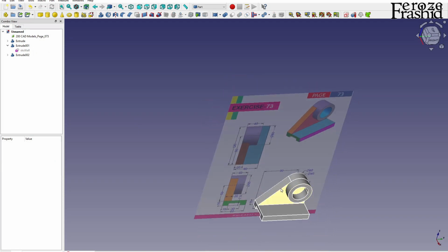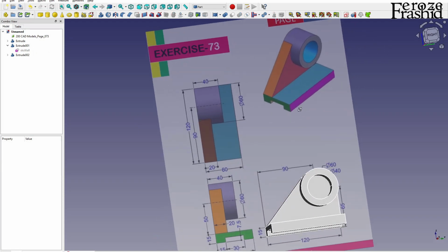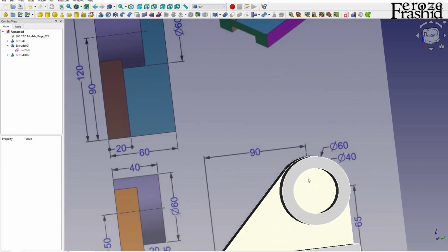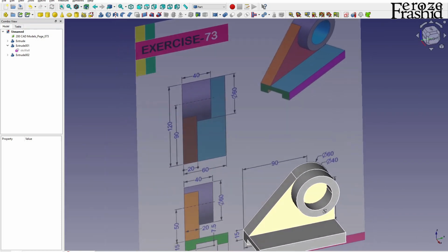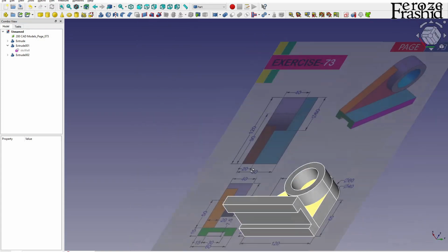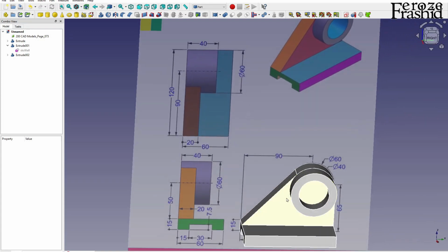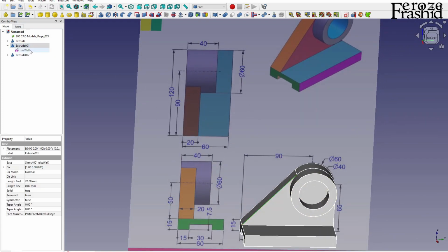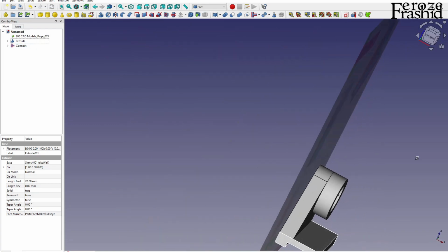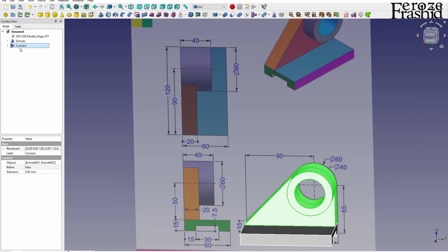So we have the wall and we have the hole, but the wall is solid up there. We want to make a hole. So let's see if we can use our connect tool to make this. I want to select this wall and this hole, this color, and come here and say connect objects. That took care of our hole. So that makes one object.